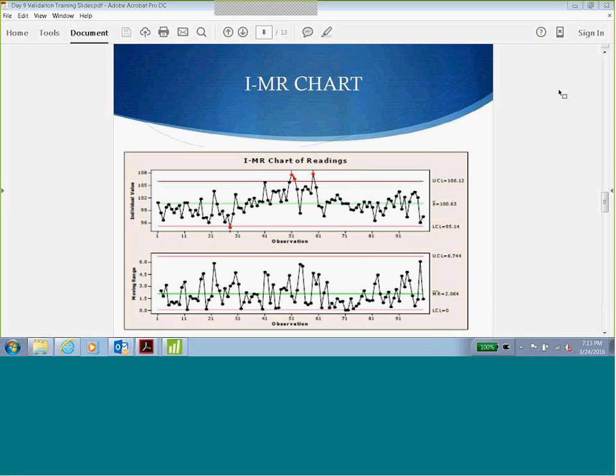Target values to your own. So imagine any product, like a chocolate bar. The weight of the chocolate bar should be 100 plus or minus 2 grams, so 100 is going to be the target. Just imagine a product or use your own information. You're going to set the upper specification limit, the lower specification limit and the target. That's always fixed. And what you're going to be doing is playing around with the samples that you're going to be collecting